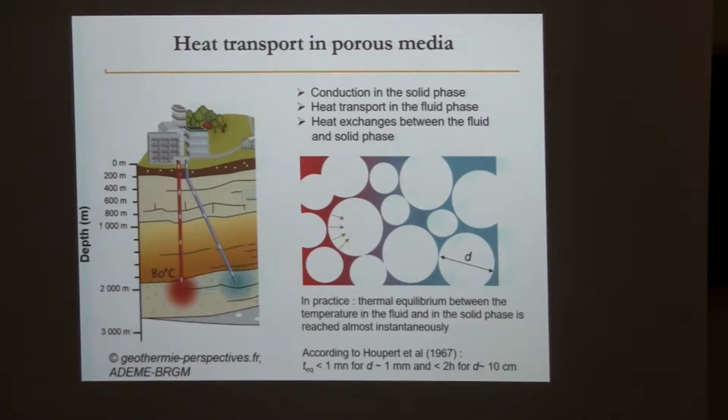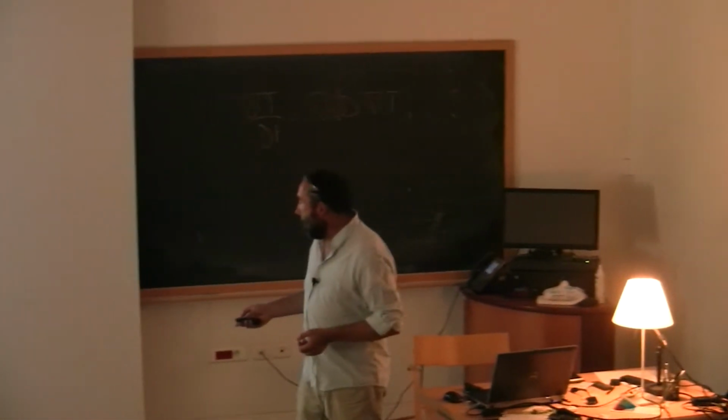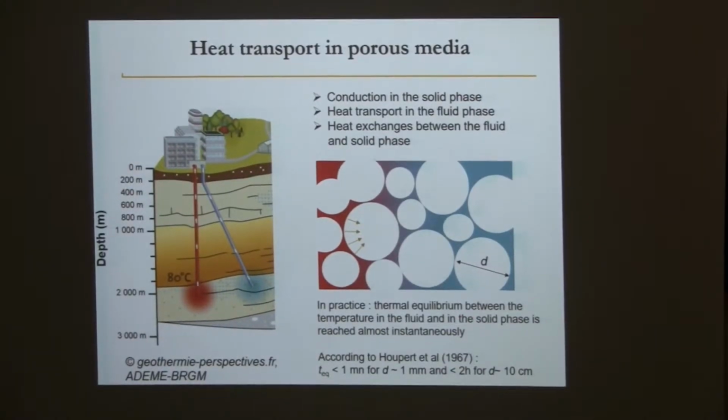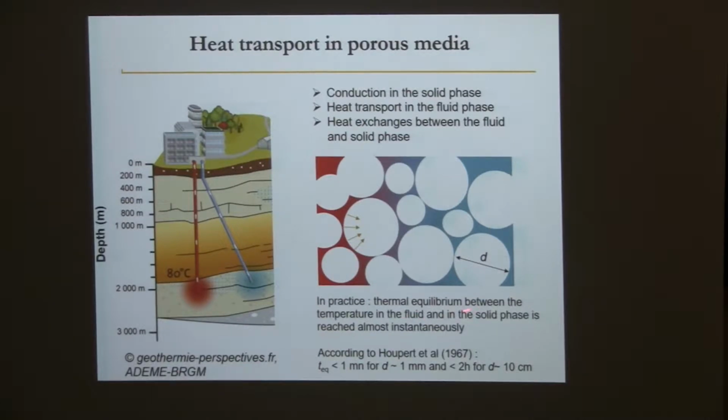Usually, to treat this problem, what is done is to assume an almost instantaneous thermal equilibrium between the temperature in the fluid and in the solid phase as the heat front passes into the porous medium. According to some work, this time is close to minutes, or longer if the size of the particles is really big. But in porous media, usually, we assume that there is an instant equilibrium.